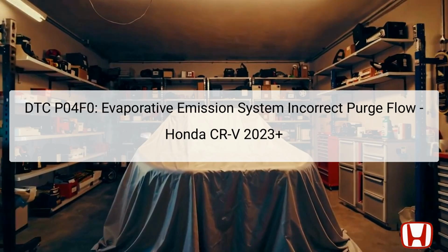The system includes several key components, such as the EVAP canister purge valve, which regulates the flow of fuel vapors, the fuel tank itself, and the EVAP canister. When the powertrain control module, PCM, detects a fault in this system, especially when the purge flow is inadequate during pressure testing, it triggers the DTC.